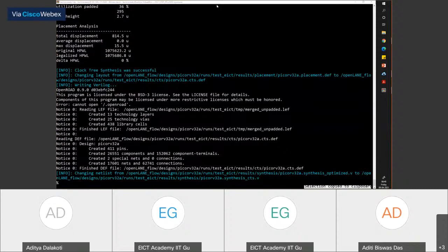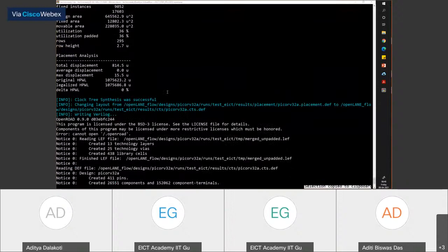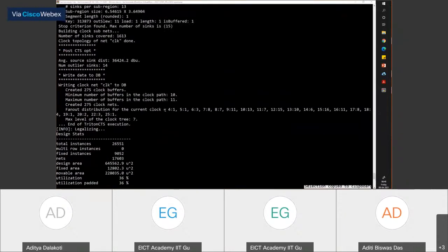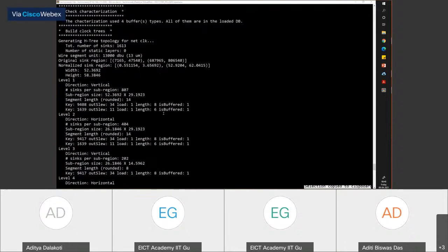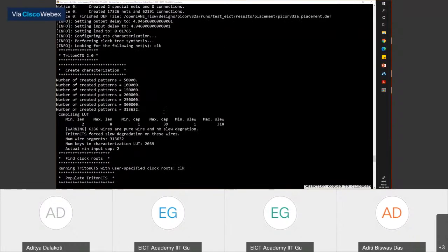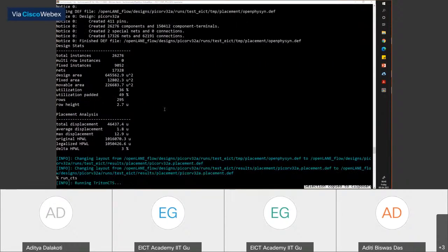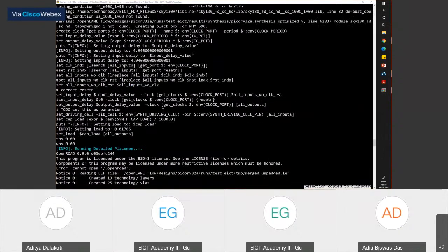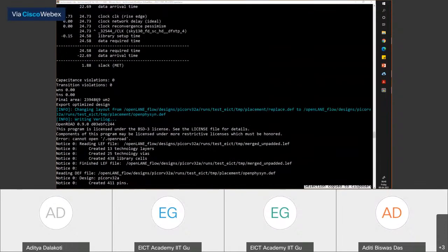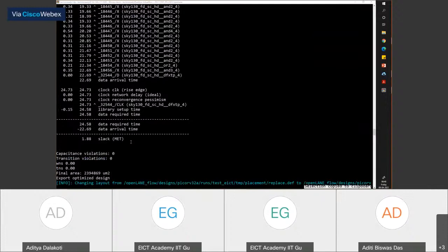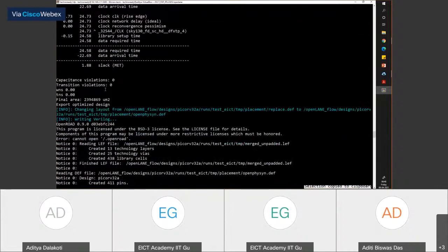So timing analysis happens after every stage. Vishnuvardhan, your tool will give you a report on different placements. So if I can actually just go here, I think over here I saw, you can go in the log file of placement and it would have run the timing analysis. So let's see, here it is loading up your STA scripts. It is trying to do timing violation, and see here, over here, it actually did timing analysis and it analyzed that it was able to meet the timing basically.